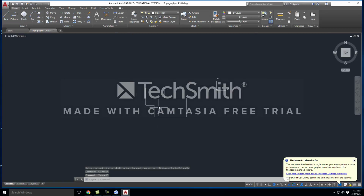Okay. Another scenario where you might use this, not just when they're intersecting, is when you might have a drawing where you have one line like that, and maybe a line that's kind of like that. You know that you want these two to trim, you want these two to come together. Obviously you could click on it and drag it out, click on this one and pull it over, but that's when CAD becomes really inefficient and it takes you forever to create things.